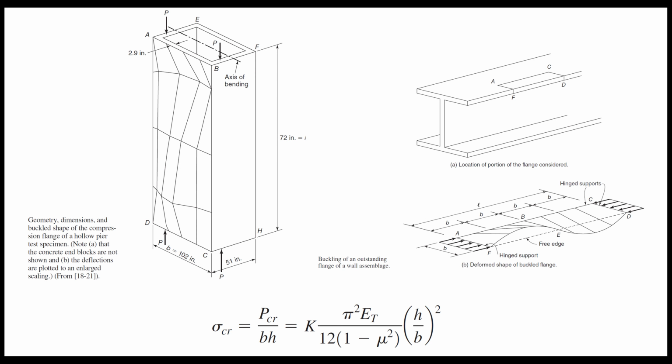Whenever the local buckling could occur, the elastic buckling for the plate could be explained using this equation. Again, the final design formula for a concrete wall or structural steel wall according to the code of practice will look slightly different due to including the effect of the material behavior such as cracking, creep, residual stress, initial imperfection, and so on. The flange of the H-shape or web of the T-shape is often referred to as unstiffened element, while the web of the H-shape or rectangular section is often referred to as a stiffened element.